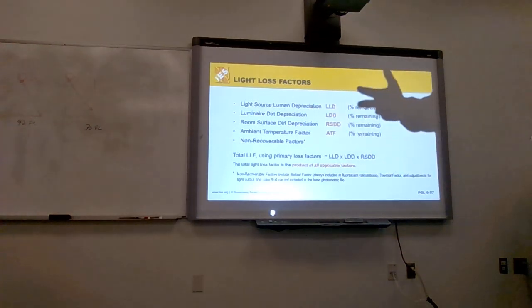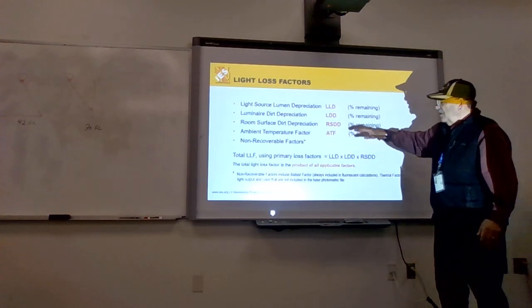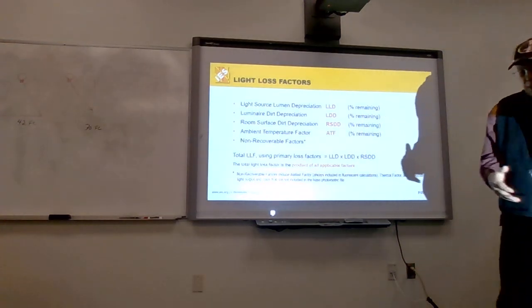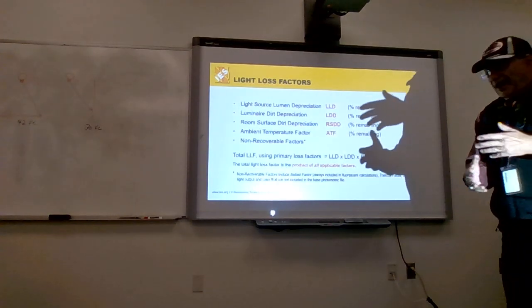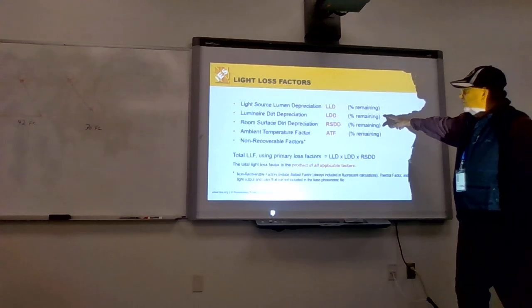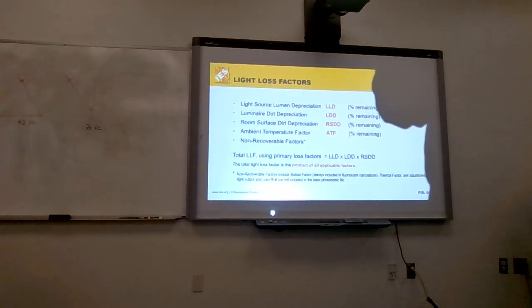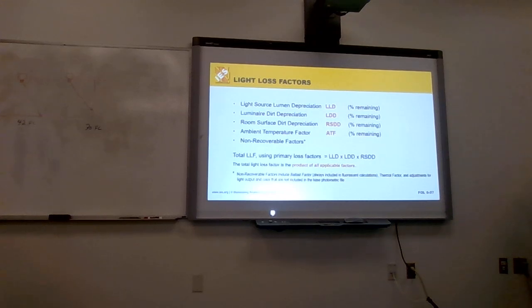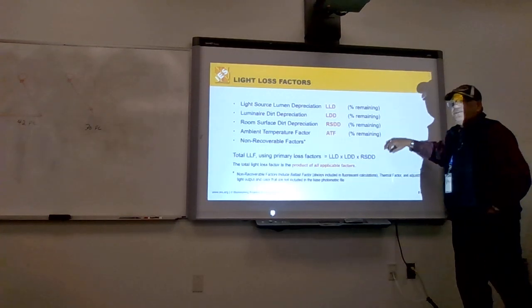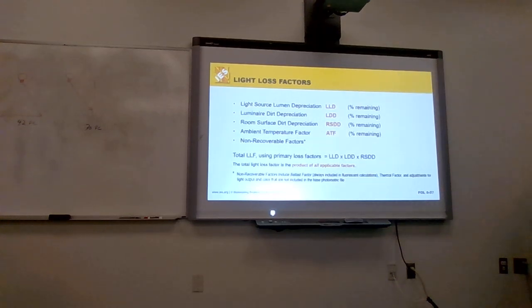So in a clean room, there's very little dirt depreciation. In a classroom, we have a little bit higher, and depending upon how much dust is collected by a wood floor or a carpet floor, will determine and alter this. So we have to calculate the carpet and the floor and what material it has. Typically what we'll do is we'll lump all of these together and come up with a number. Okay, and I will discuss that as we go through this.